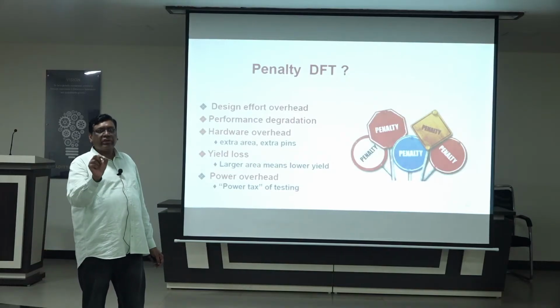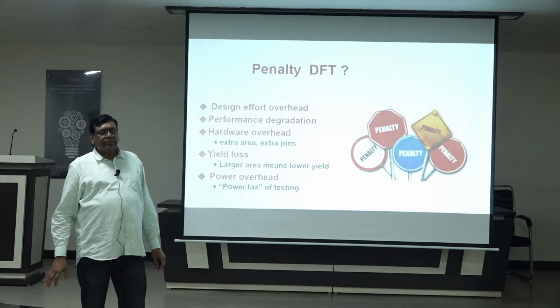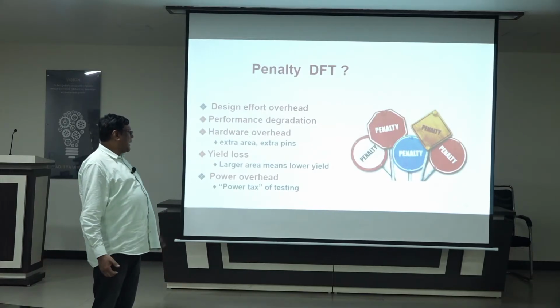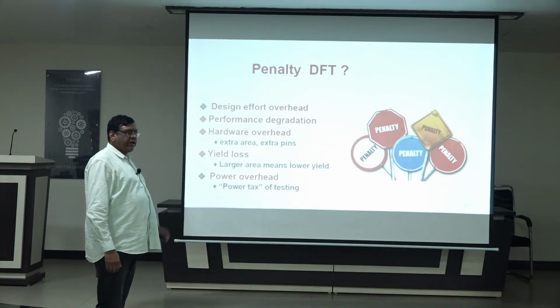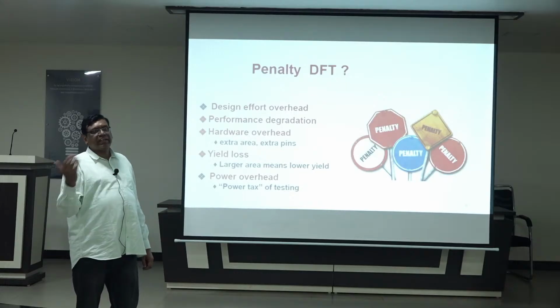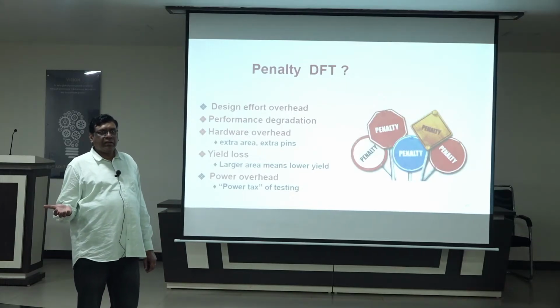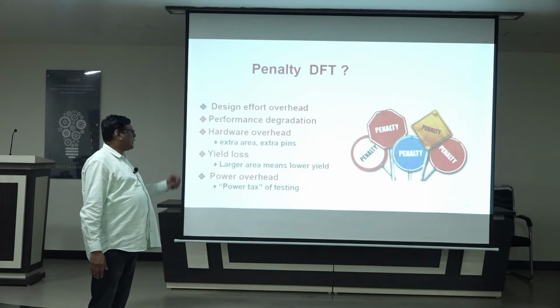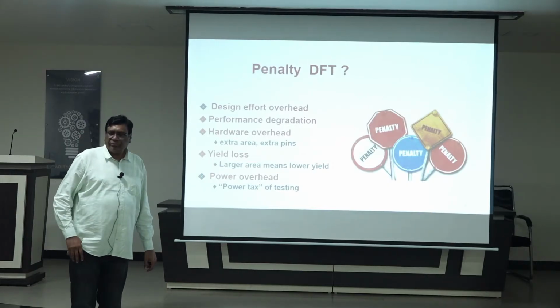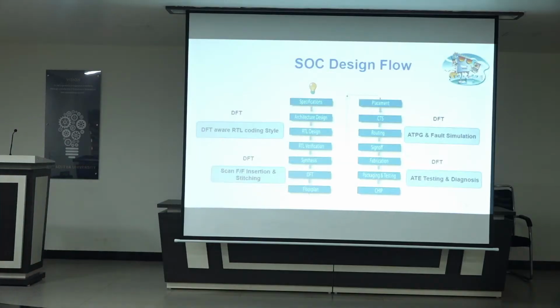Ultimately we have to test each and every transistor, so at the expense of that I am doing DFT. These are the different penalties. Power overhead, power burden, power dissipation will also be more, because we are keeping an extra 30% hardware. For that we will have a power tax, and yield will also be slightly affected. And the speed will reduce.